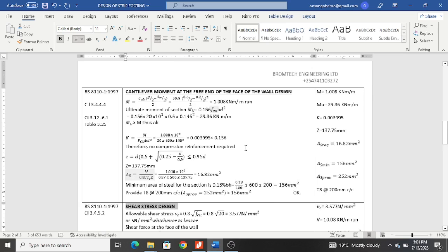Then we will be done for that section. So the moment is obtained by this formula, where we are now going to start using Q ult, because we use the ultimate moment for design, but we use the service loads for sizing and maybe carrying out serviceability checks.